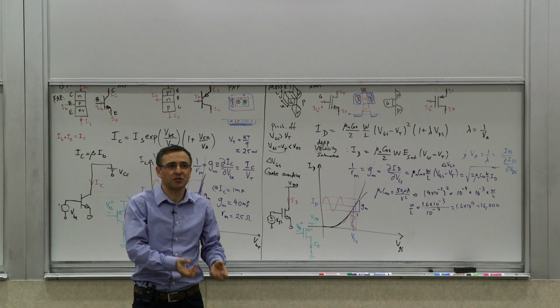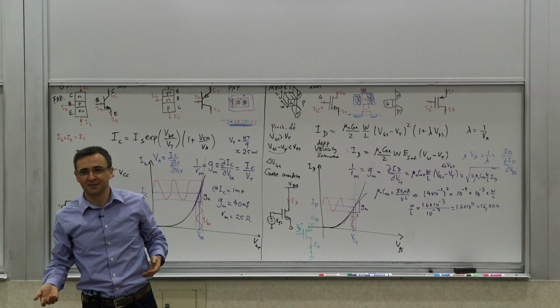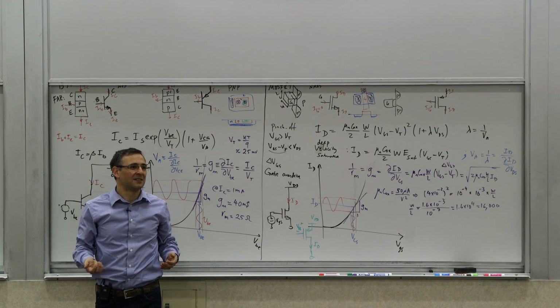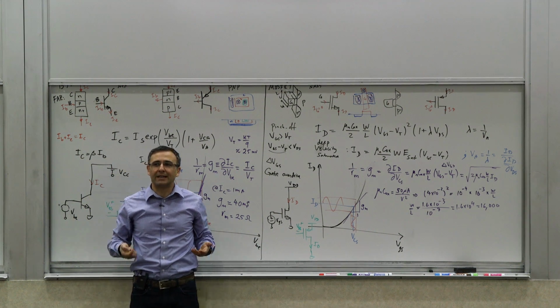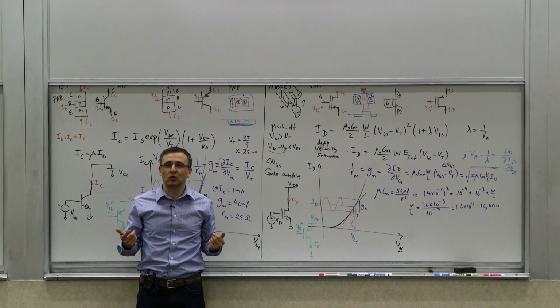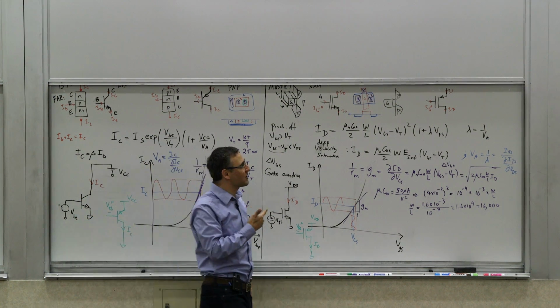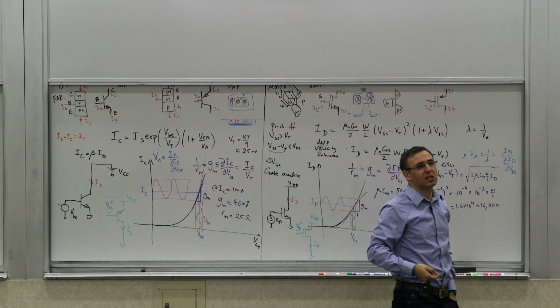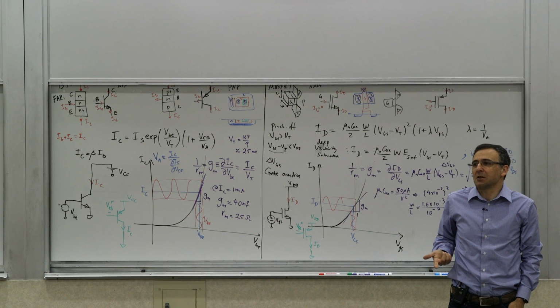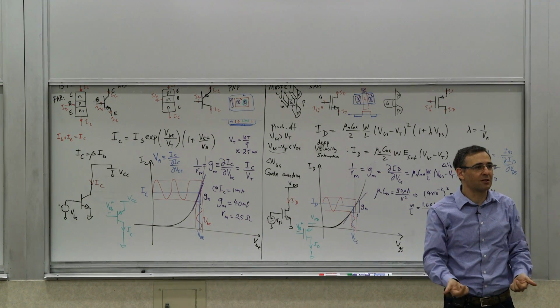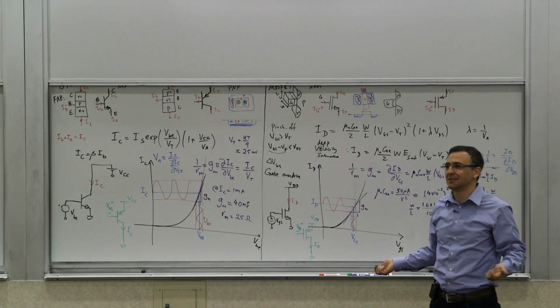Because all that minority charge carrier, most of it needs to go into the collector. And it does not turn off easily. So making logic gates for these things, the way we make it with MOS transistors, is hard, because with a MOS transistor, we just let them go into the triode region. Fine. They still go into the drain and source. They were majority charge carriers anyway.